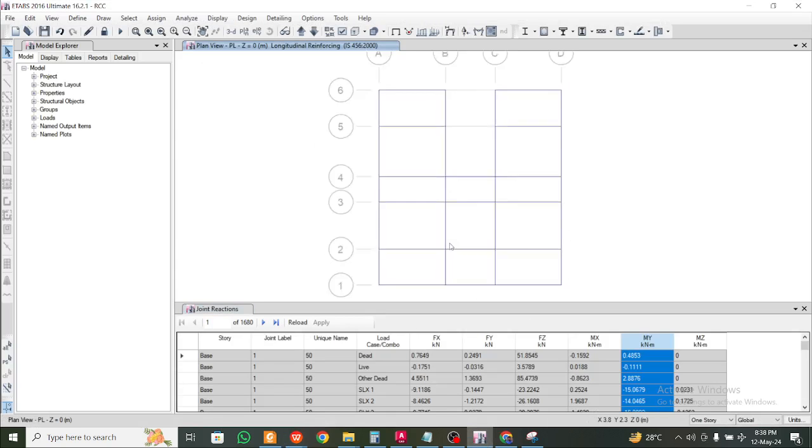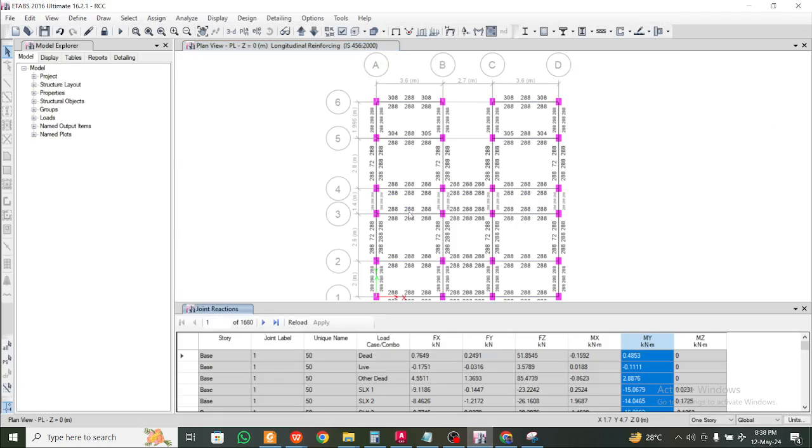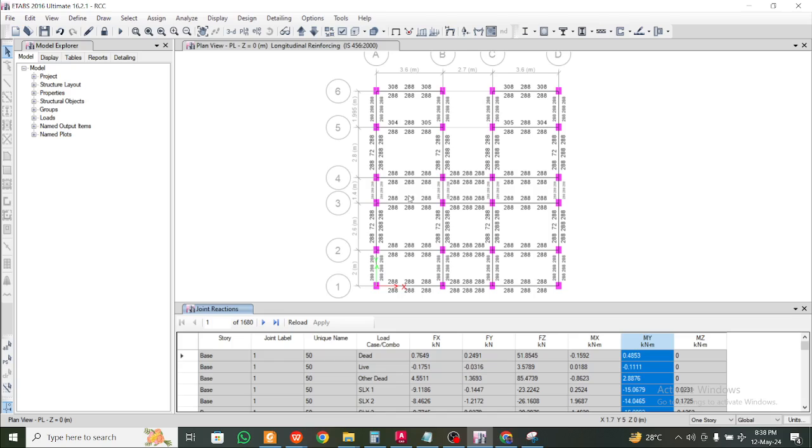So my goal was, if you want to design a building, to take you through the entire steps, not just show the analysis, not just show the shear force, bending moment and all. You are a structural designer, you need to design a building, give the final drawings, make them yourself or give them to a draftsperson, but you need to have the final results ready. So that's how you get the final results ready. We have seen the beam design, we've shown the column design, and we've shown the procedure to go for the foundation design. And for the slab design as well, you can just check the spans of the slab, and you can design using any Excel sheet which is available. I recommend you get a paid, superior Excel sheet, or you can do it using manual analysis calculations as well.